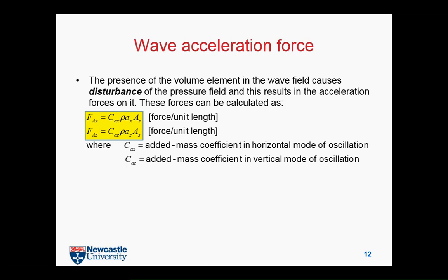And then maybe you can use another coefficient, but the value will be 1 plus the coefficient for added mass. So that's why sometimes you can see this. When you use the mass, we use the coefficient multiplied by real mass of your structure. So basically M is the one you're going to multiply with your AZ or probably AX. Yes, that's the mass you need to use.